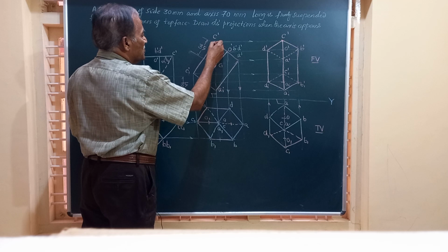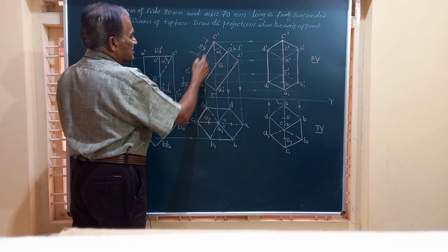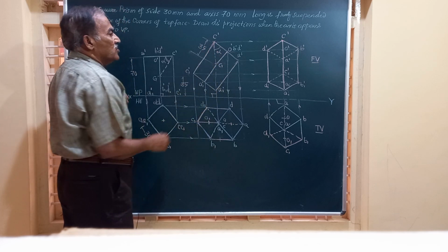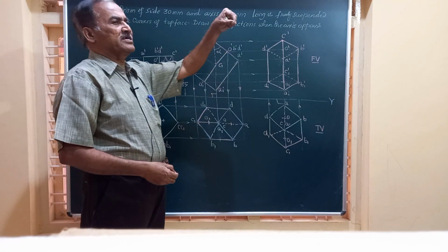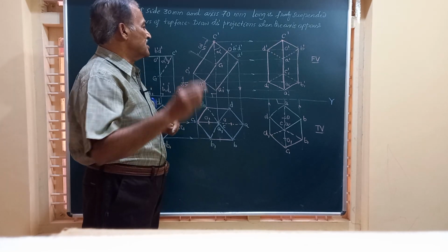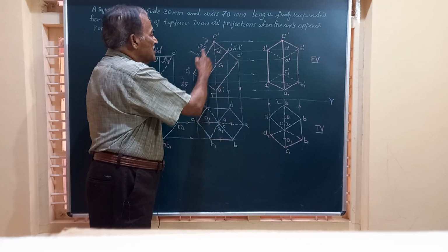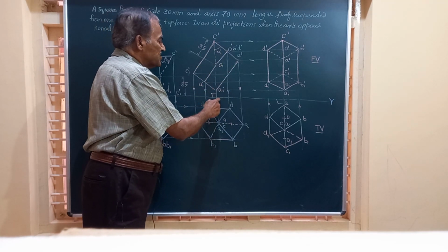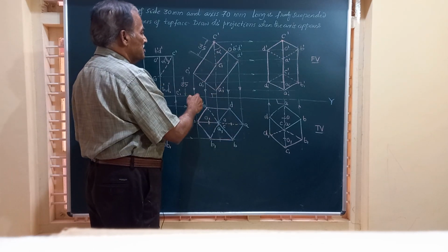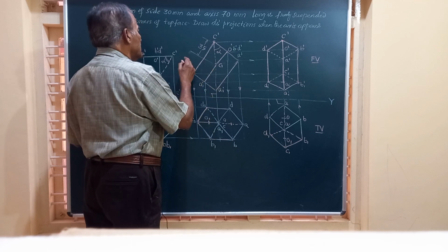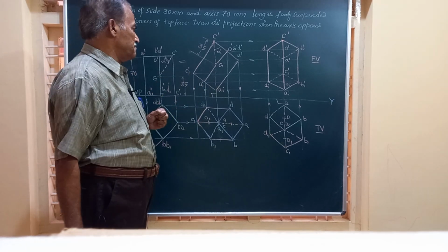Friends, once you have that, you can obtain these three lines by drawing parallel to this line here. Now this is how the object looks when it is suspended from a point C dash by a small thread, say. Friends, here you should remember, since it is freely suspended, none of the parts of the solid should touch the XY line. Now friends, for this position, which is very important, and remember, this is exactly equal to this first figure. These two are exactly the same.